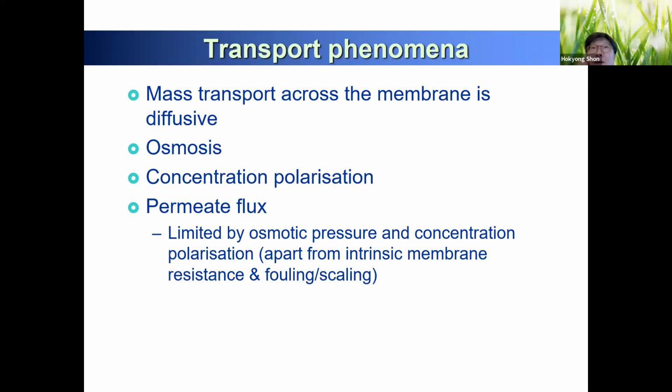You need a lot of calculation there because osmotic pressure is involved. Your water concentration keeps changing, like seawater at 3.5% TDS. In one element you have pure water and high brine water, so your concentration is high, which means osmotic pressure is high. Then you go to the second element, third element, and you keep changing your osmotic pressure.